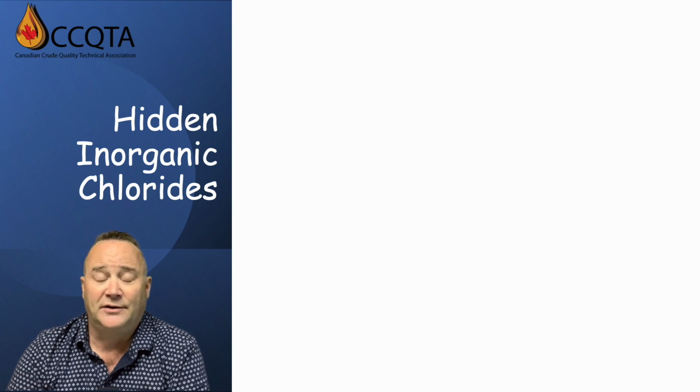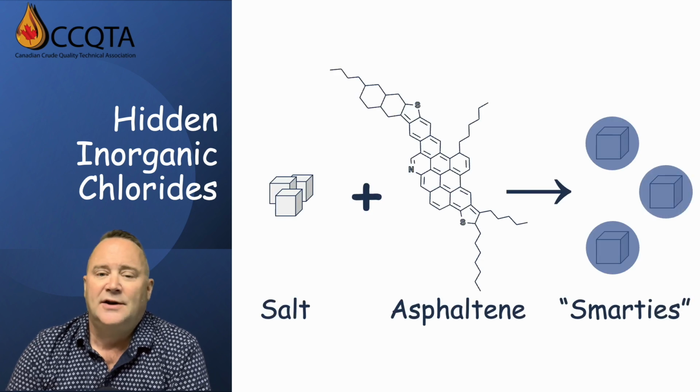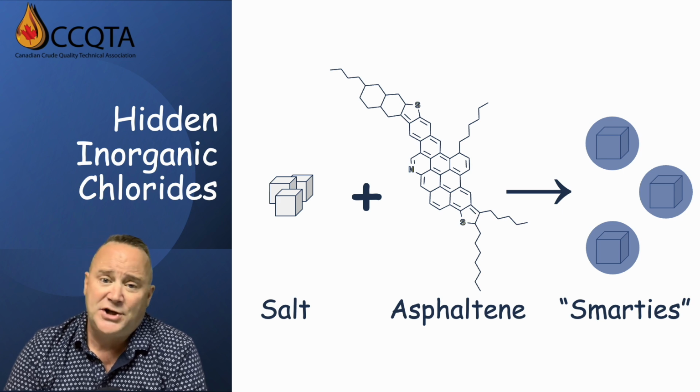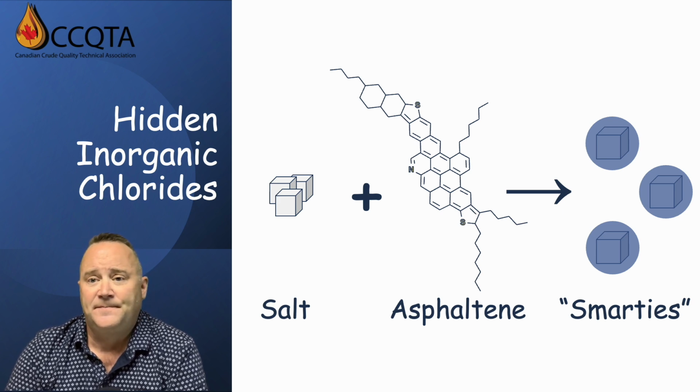A detailed investigation determined that slop treatment practices at the production site involved the use of a flash evaporator like we talked about earlier. These oil-coated solids, or Smarties, were effectively undetectable at the source and only partially reported at the delivery point. These samples were collected and tested following thousands of kilometers of turbulent pipeline flow and the shearing action in pump stations. As a result, some of the crystalline salt was dissolved during transport.